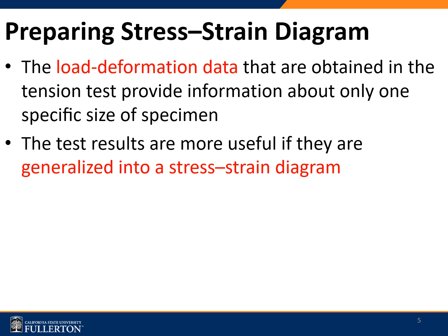So why is the stress-strain diagram more beneficial than load deformation diagram? It's simply because the stress-strain diagram eliminates the sample specific property, which is the cross-sectional area or the original length of that particular sample, and it's more generalized for a material rather than a specimen.